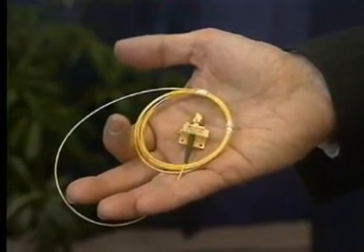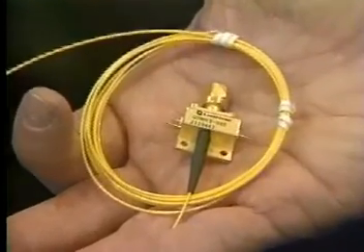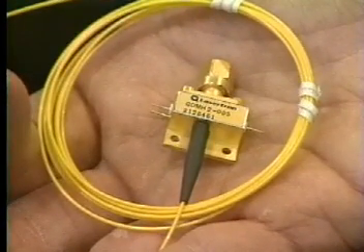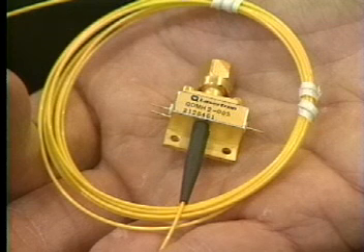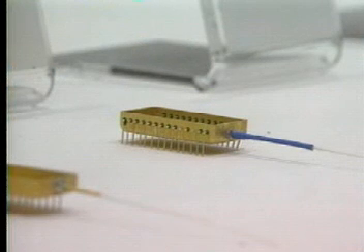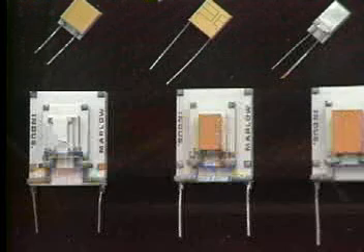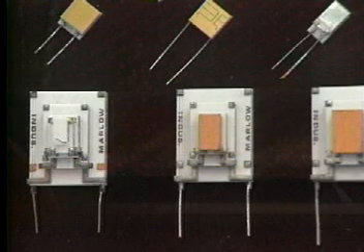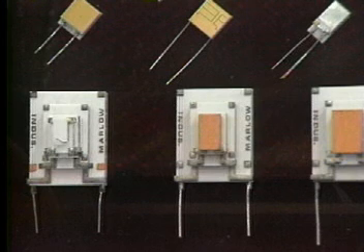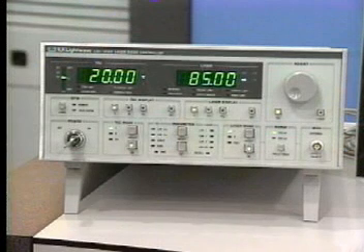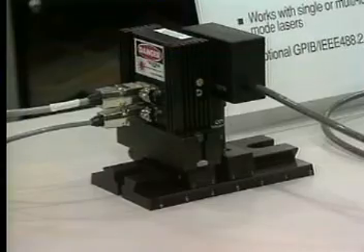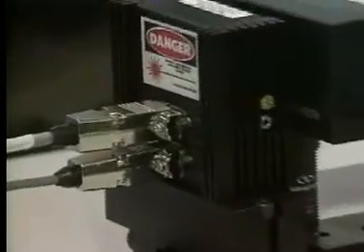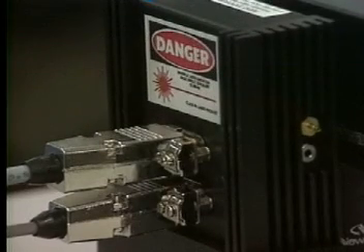Lasers are very sensitive to temperature changes and power supply quality. Their output can change significantly in both intensity and wavelength for a minuscule change in temperature. Even small lasers packaged with drive electronics can dissipate over a watt of heat. For this reason, thermoelectric coolers using the Peltier effect are added to stabilize the temperature of the laser package. The Peltier cooler is controlled by a closed-loop temperature servo system using a thermistor to sense the temperature of the laser and adjust it accordingly to keep it within a fraction of a degree. The hot side of the cooler is thermally connected to the outside of the laser package, so adequate heat sinking must be provided.